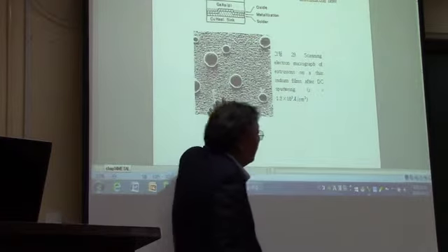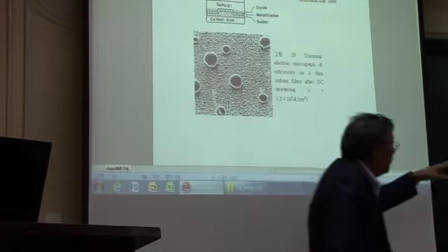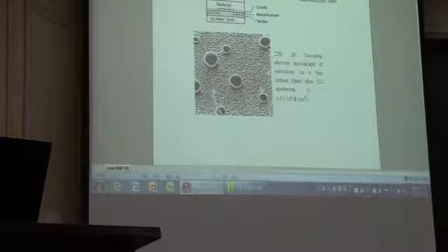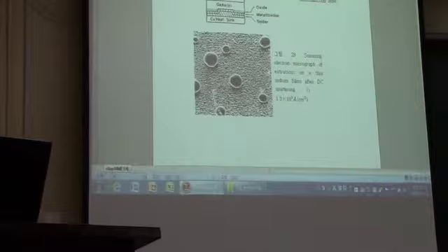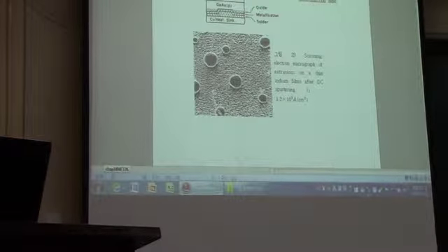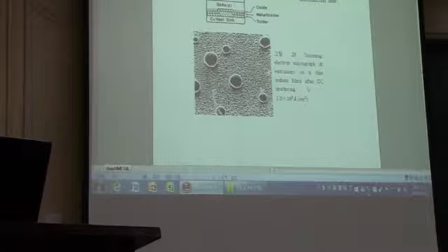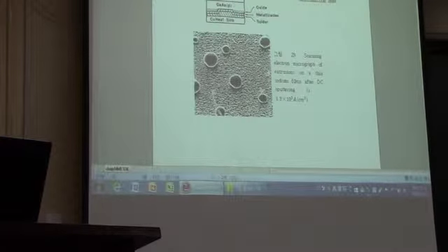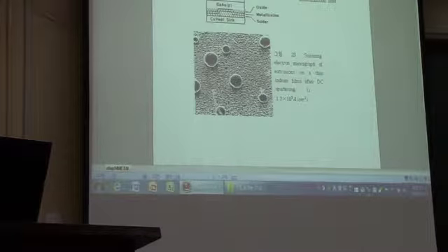This whisker will give you a short. Let's suppose you have a metal line, something like this. It's aligned with something like this. And then if a whisker grows from some part of this metal line and touches the next nearest metal line, then these two metal lines are going to give us a short. So this whisker is not a trivial problem.